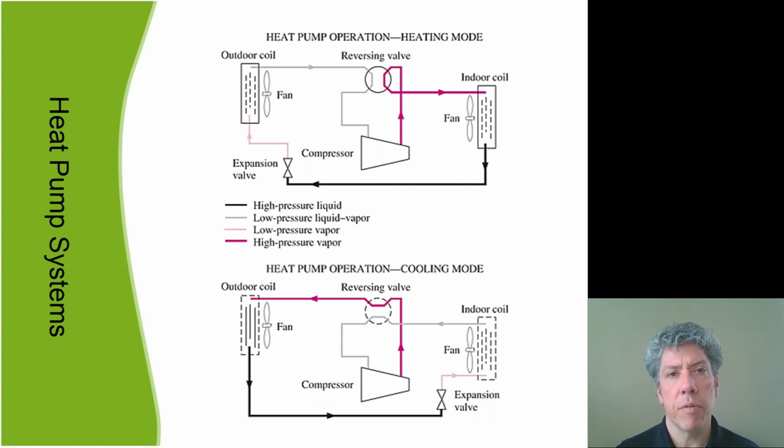Now, once the refrigerant has gone through the outdoor coil, typically it's controlled such that the refrigerant comes into the outdoor coil, which would then be called the condenser. It goes into the outdoor coil as a gas and comes out as a liquid. In other words, you have a high enough pressure where even though the temperature can end up being 105, 110 degrees of the refrigerant, it will still end up being a saturated liquid because the pressure is so high. So that black line comes out of the outdoor coil and feeds into the expansion valve or the throttling device.